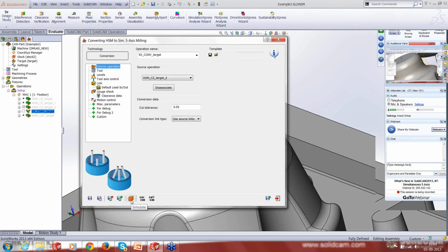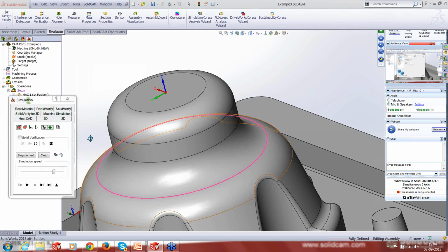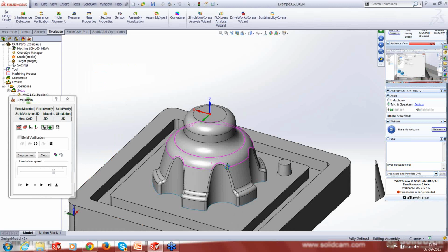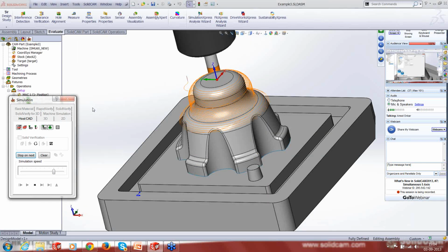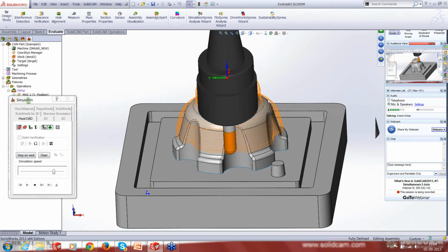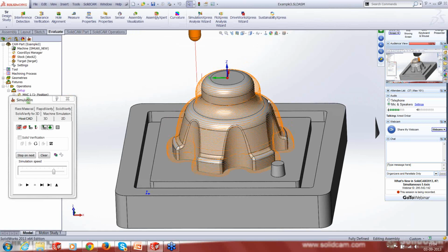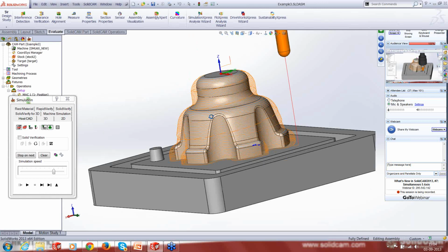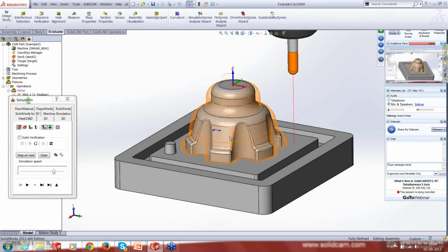All right, yes, so the toolpath is ready. Sorry, Eddie, I'm just done. Just a moment. So if you now look at the simulation, all those funny retracts have now disappeared. We've got nothing now with any of these pretty clean toolpaths. So now you know what those options are.